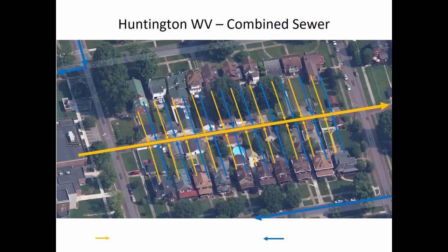And that's really a problem at the treatment plant because they have the flows that they have to treat during dry weather, which is mainly people flushing their toilets and taking showers and washing dishes. But then when it's wet and rain starts to fall on roofs, and when the groundwater table rises and foundation drains kick in, then there's this runoff water as well, entering the same sewer.